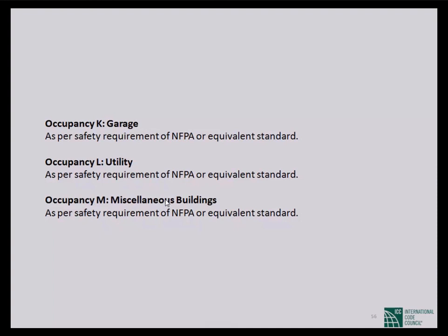So you need detail of this miscellaneous building. Actually, miscellaneous cannot be defined. You can have a different type of building. So for detail, you have to go to NFPA. For example, if it is a metro station or a bus station, then you have to go to NFPA 130. Actually, nothing is given in BNBC.